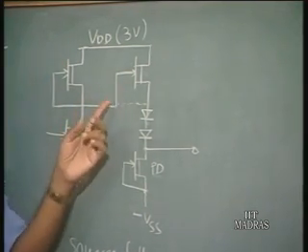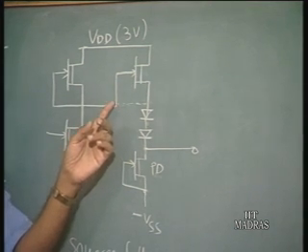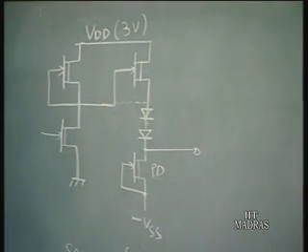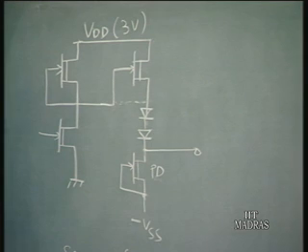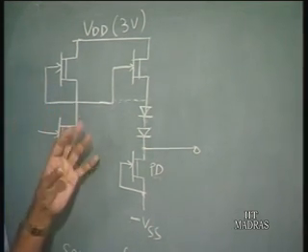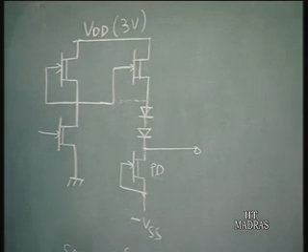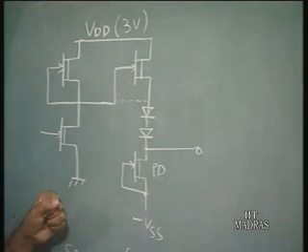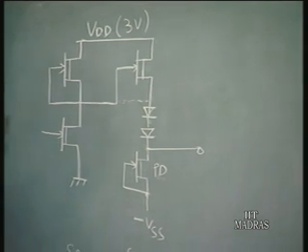We have a source follower, that is, whatever is the gate voltage, you have a similar voltage at the source. So from the output characteristics point of view, these are identical, but this circuit has a much better performance during the switching period.